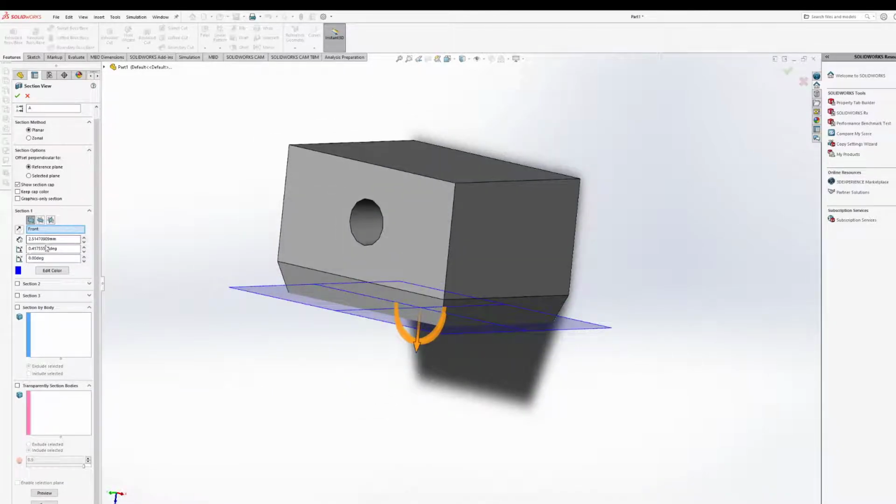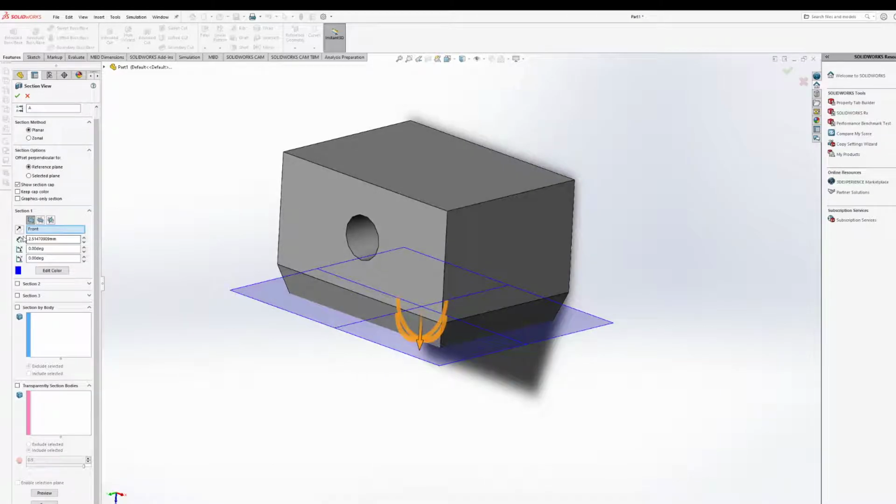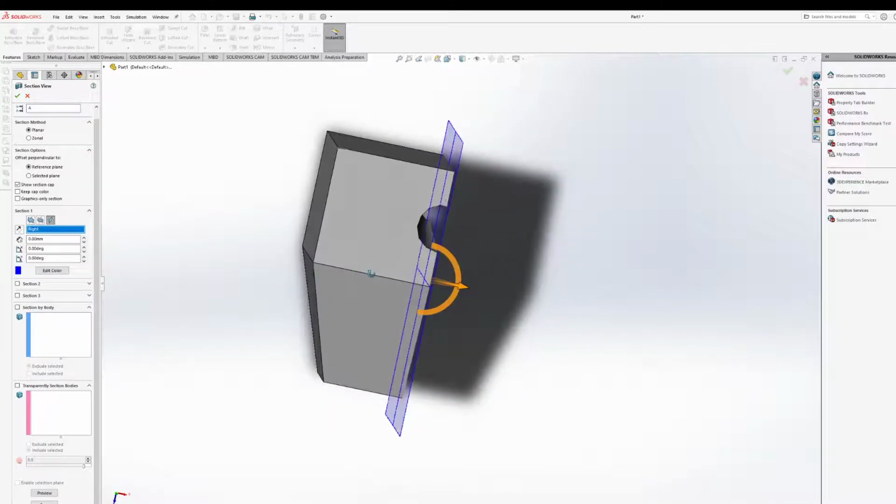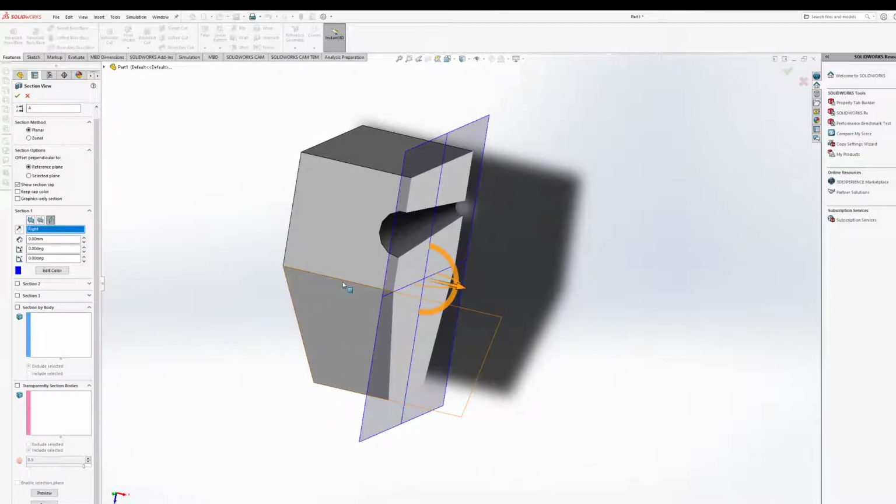And then it gives angles in the X and Y direction as well. I like to keep it as just 0 degrees just so that everything is parallel to each other. But if I wanted to, I could cut it from the right plane instead. So it's nice that just clicking on those buttons is going to show you where that cross-section plane is actually starting from.